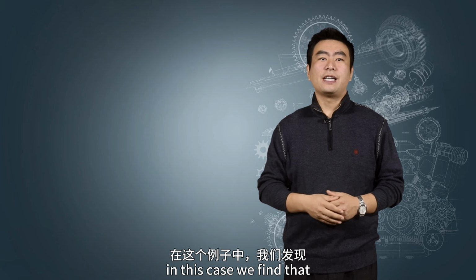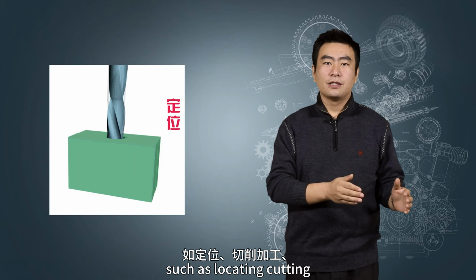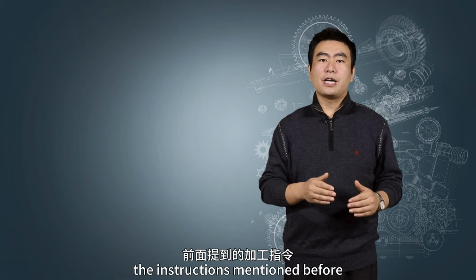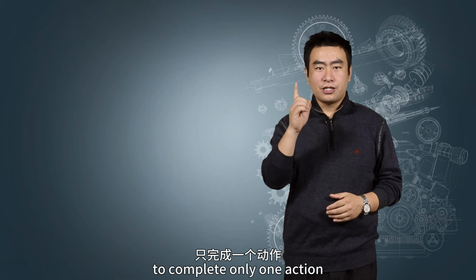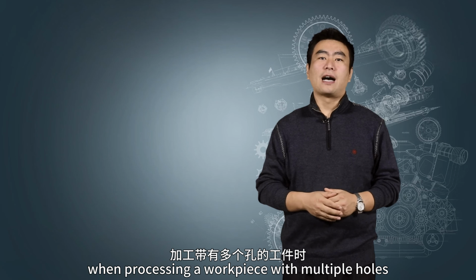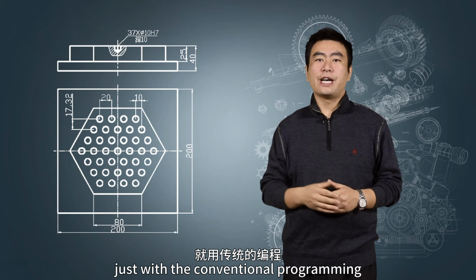In this case, we find that the processing of a hole requires actions such as locating, cutting, pausing, and retracting. The instructions mentioned before share a common feature: one program segment can only control the machine tool to complete one action. This programming is not so complex for a few holes, but it will be troublesome when processing a workpiece with multiple holes with just conventional programming.